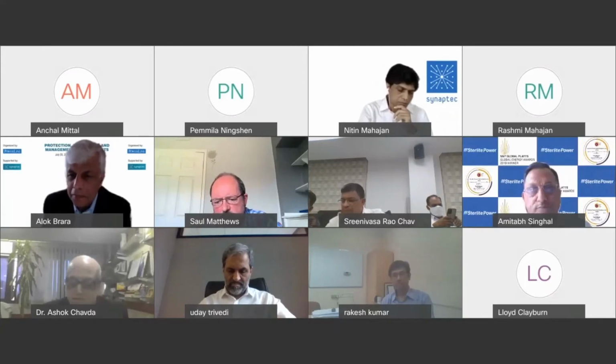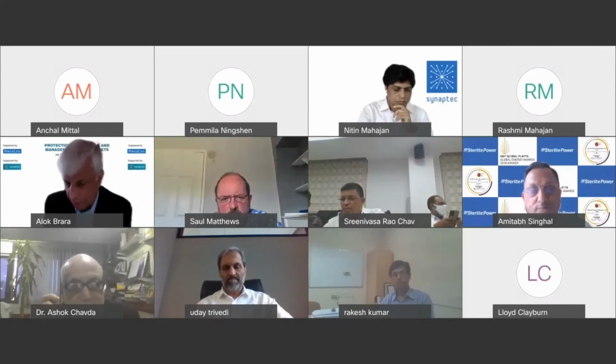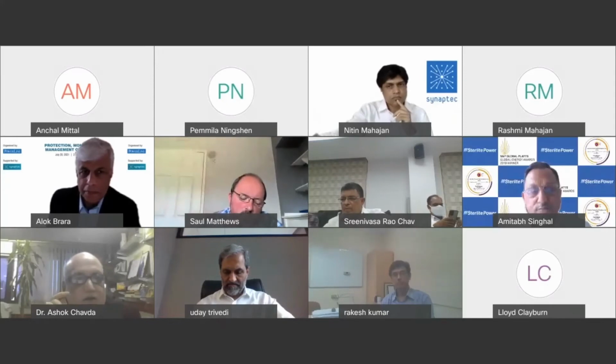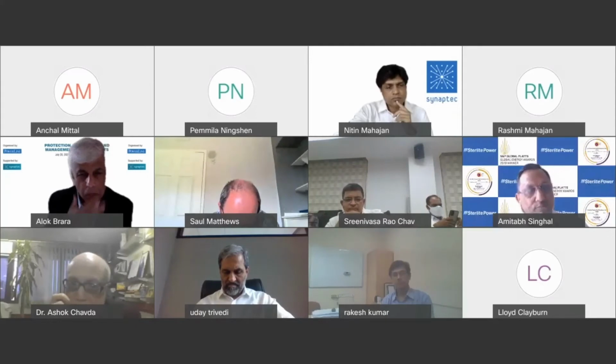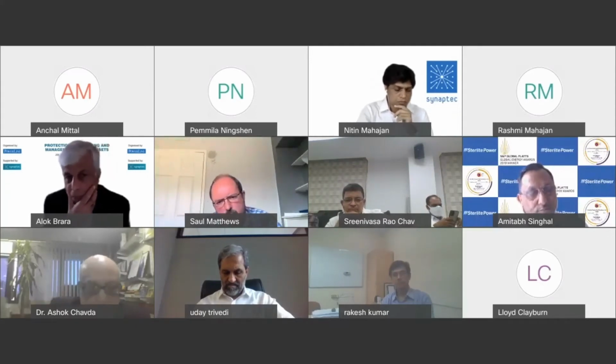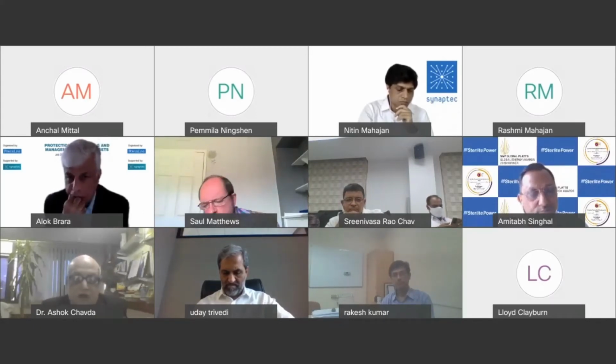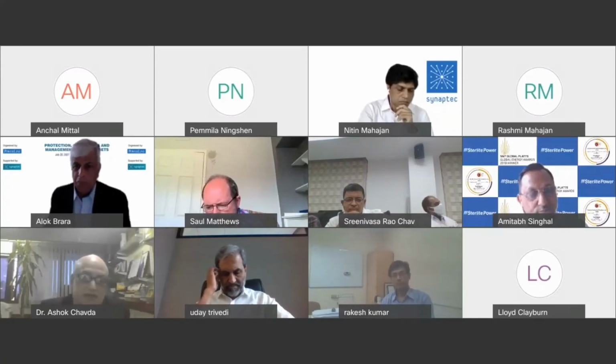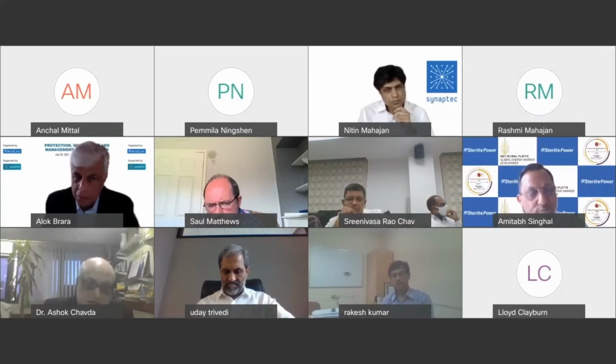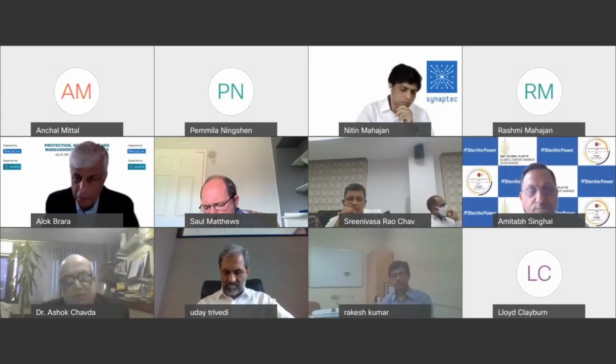And who are using these? One more thing I want to clarify, if time permits. Particularly on tan delta, we have carried out one best solution: we have created a logic that depends not only on the value, but also on time. Not only the value, but it depends on the time. So we calculate the rate of rise, and accordingly the tan delta results suggest replacement or retesting.